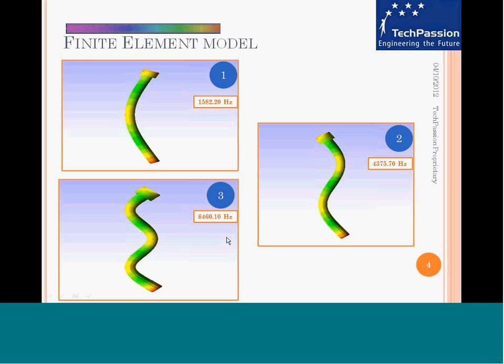So we first performed the finite element analysis, and there was no way of modeling defects into this unless we get into very detailed material constitutive modeling. So we are looking at it at a very macro scale. We took the bolt, did three boundary conditions, used 10-nodal tetrahedral elements, and performed modal analysis to extract the first three natural frequencies.